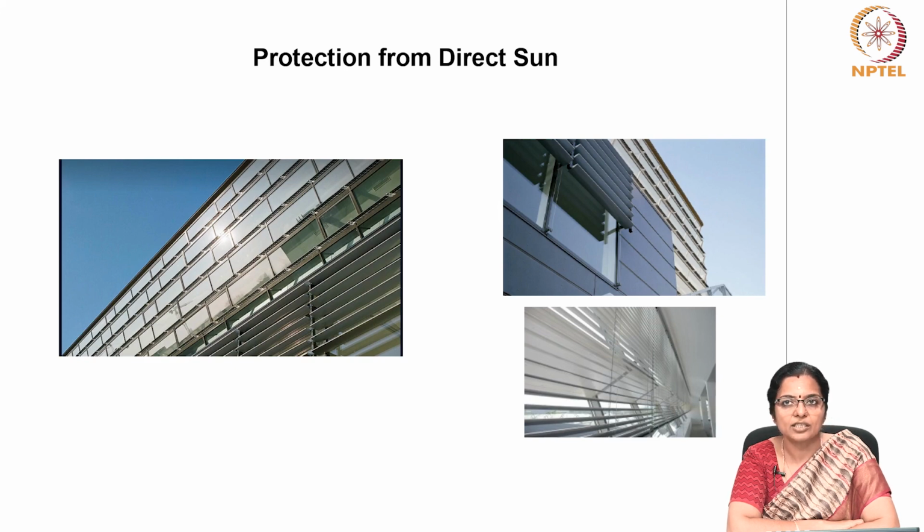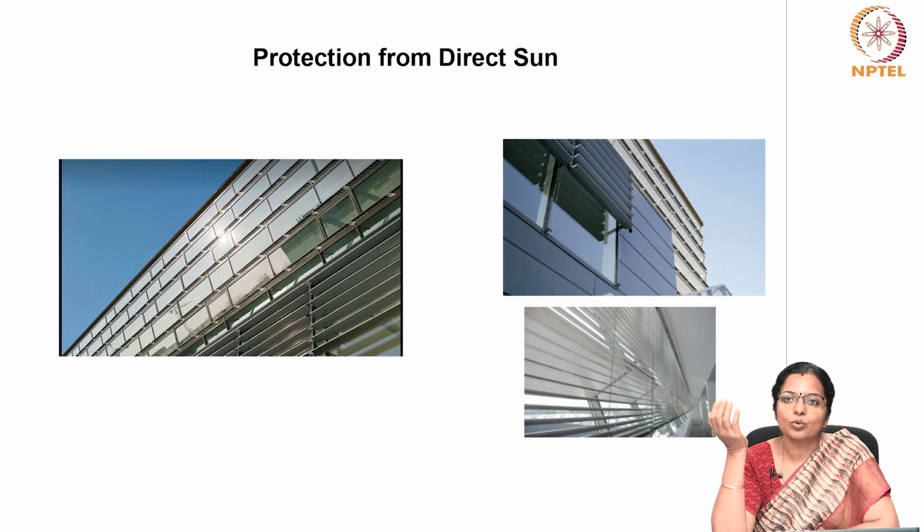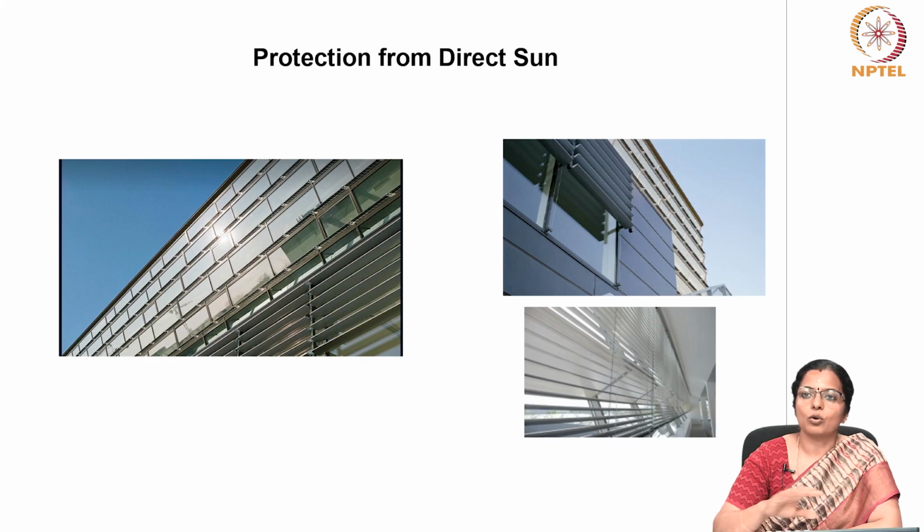In winter, when the sun is low, its heat is captured and fed indirectly to the rooms on the north side of the building through customized ducting. The sunscreen, made of perforated lamellae, is located just behind the angled facade, and waste air from the entire story is vented at ceiling level. Because of this, heated air is drawn upwards behind the facade to the vents instead of spreading out into the space indoors. On sunny winter days, this air passes through a heat exchanger in which fresh air from outside is